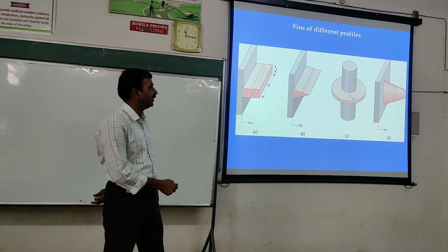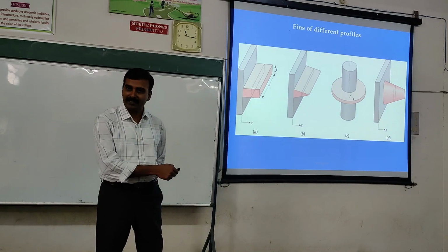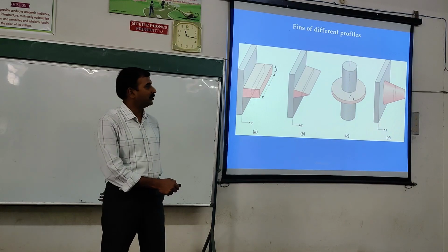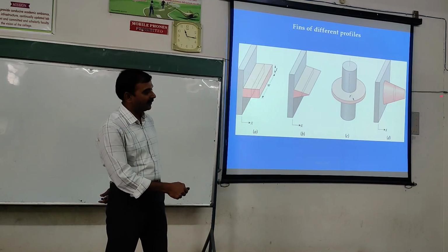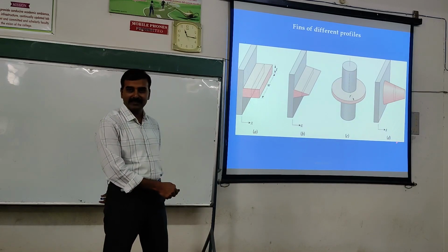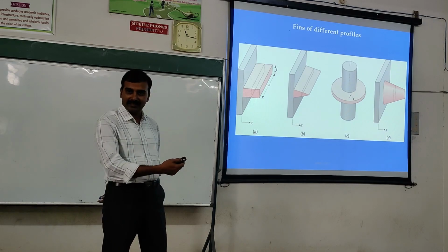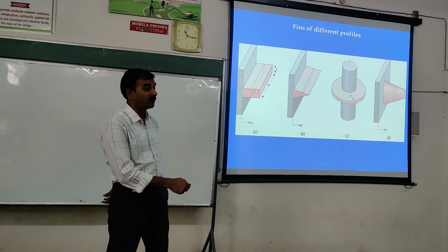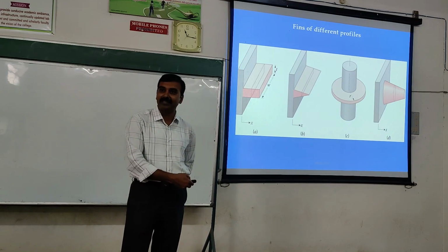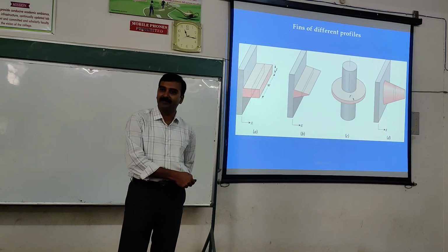Of course, you can do it, and each of these cases you should consider separately and then solve it. Now you should know what is the diameter here, what is the diameter here, and how the diameter varies with x, right? So accordingly you take the AC inside the integration or differentiation and then do it. Right? There cannot be one single formula which suits all. Each case is different, okay? Because the nature of changing cross-sectional area is different.